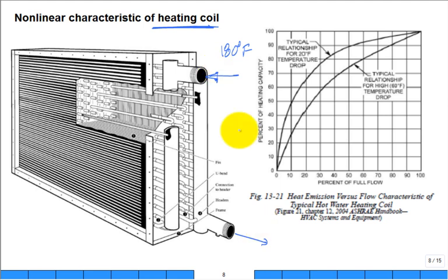And I think it's only a delta T of about 20 degrees F. The design engineers picked this. So guess what? It goes out at 160 F. That's the design. This is to run on the coldest day in this city. You go up to Chicago, well, they're going to have a different cold day design for their buildings.